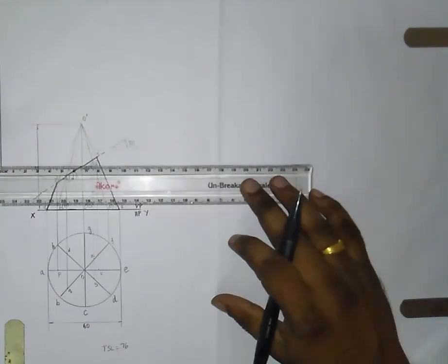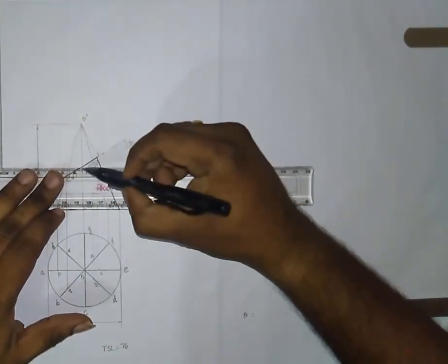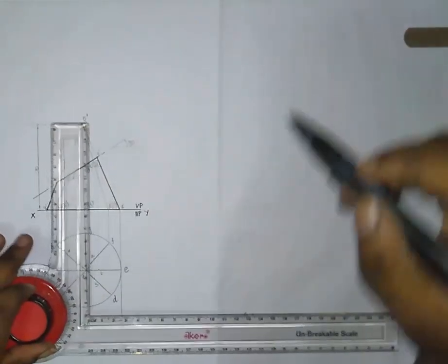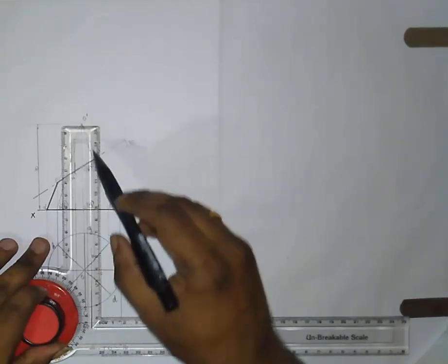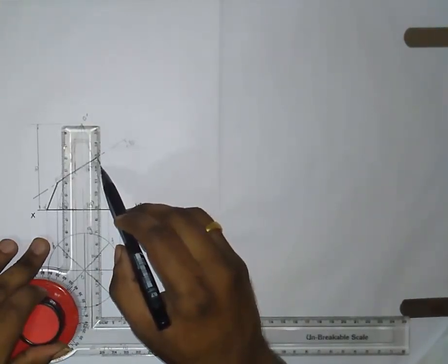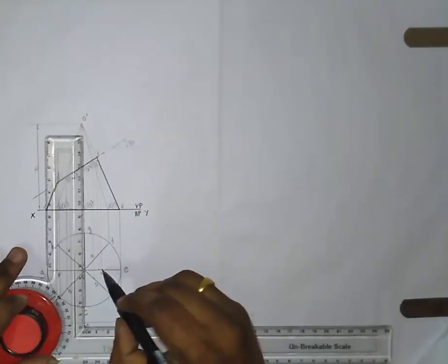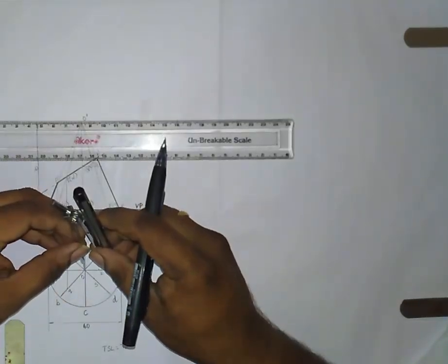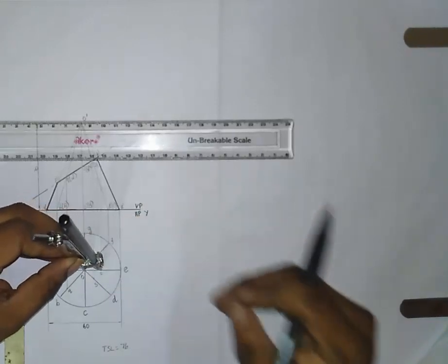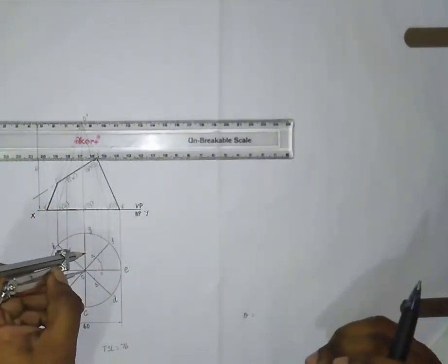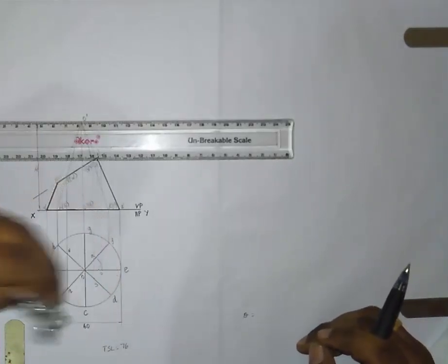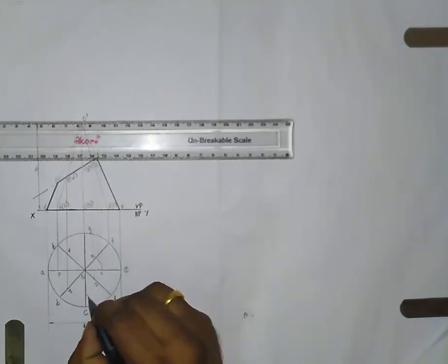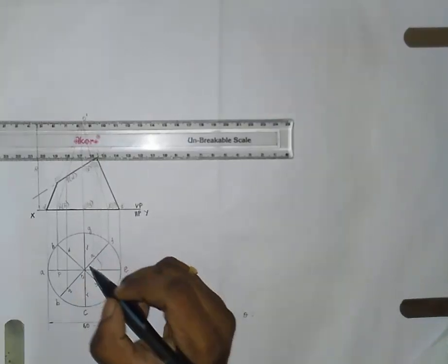What you should do is draw a horizontal line up to the true slant length, and that point has to be transferred up to the OE line. Since that point is on OE, this point has to be transferred up to OE. Now that point has to be rotated in order to get those cutting points like this. Similarly here. Now these two are the cutting points. This is the visible cutting point R. This is the invisible cutting point V.